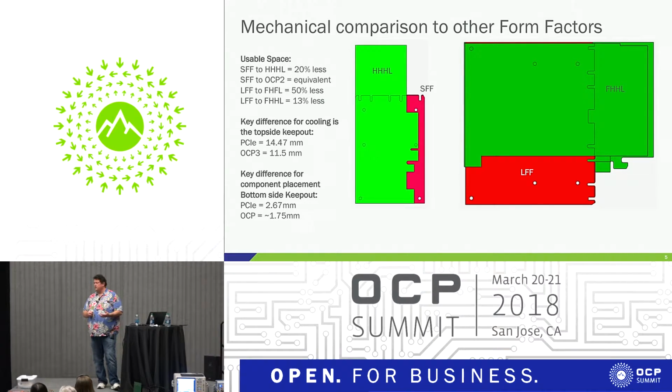And so there is still a huge demand going forward for low profile PCIe cards and full height PCIe cards, but low profile to compare with our small form factor, because you can get another 4 millimeters, 4.17 millimeters of height on your heatsink, which is a huge amount for the thermal aspect. So we've made dramatic improvements, and then Yao Ming explained how that could be extended in the future because it's facing up now. Well, you can do something custom with a faceplate and your chassis, and you can handle more power on the card.